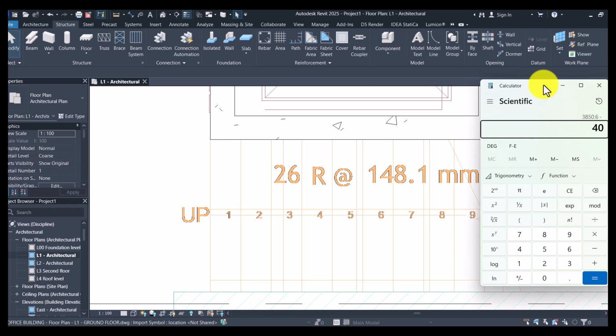So actually they're supposed to be 27 risers, not 26. So if I'm to go by 27, okay, let me see. 4 meters divided by 150. So that gives us 27 risers at 150. So that is exactly what we are going to do now.